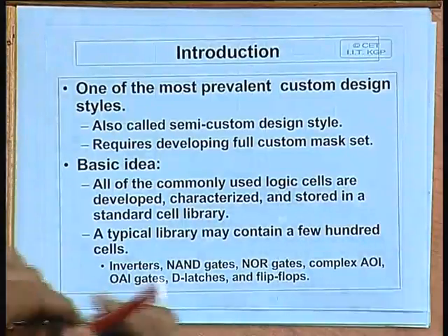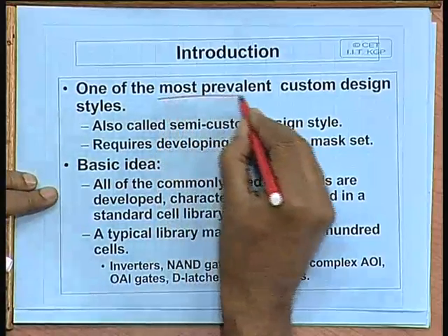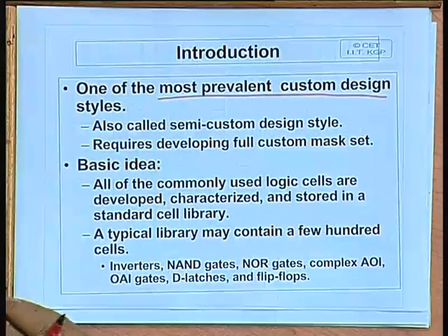But if you want even higher speed, even higher performance, then you will have to carry out each step of fabrication depending upon your requirement. Do not just start with an array of gates and try to interconnect them to make a flip flop, for example. So the next step up the ladder is something called standard cell based design. This is also called semi-custom. In fact, this is the most commonly used design style today.